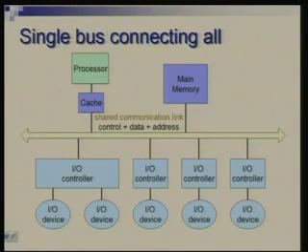An alternative to this is a shared set of wires, which is called a bus. So, a bus is nothing but a shared communication link where different types of information flow. It is a collection of basically wires and signals which are carried on these wires, which will connect two or more subsystems. So, the same wires run through everything.